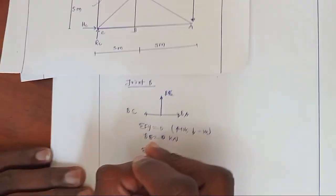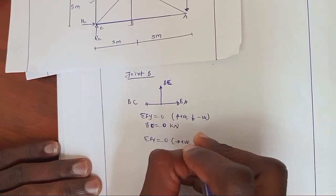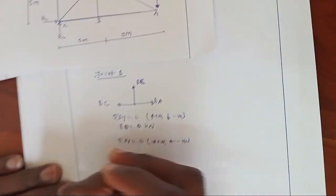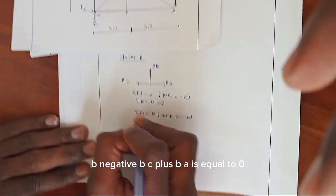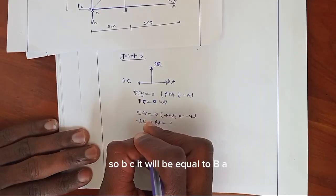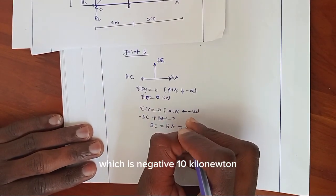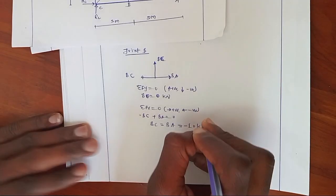Now, summation of horizontal force is equal to 0. Positive right, negative left. Negative BC plus BA is equal to 0. So BC will be equal to BA, which is negative 10 kilonewton.